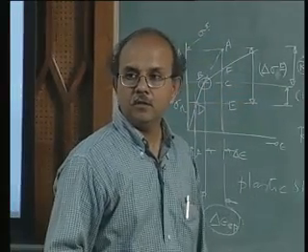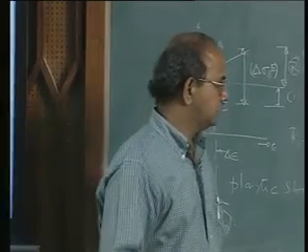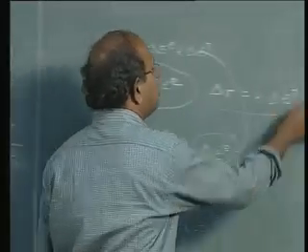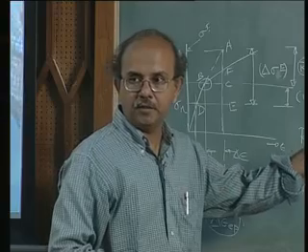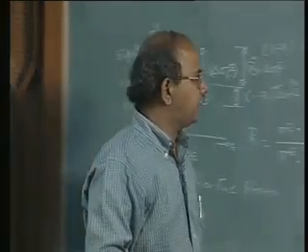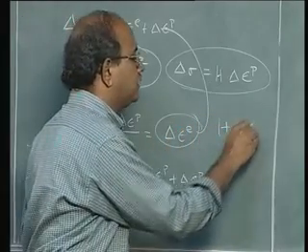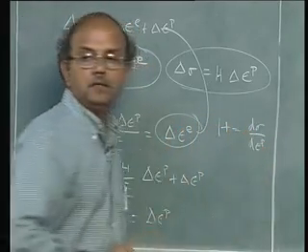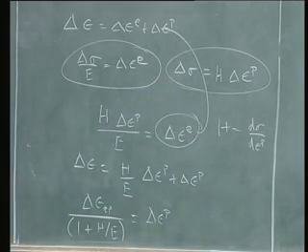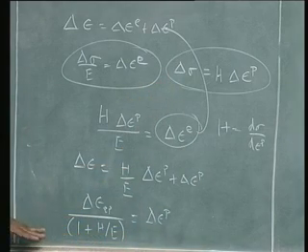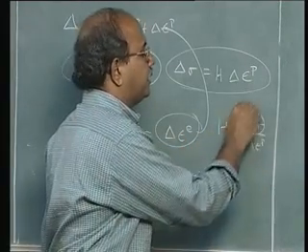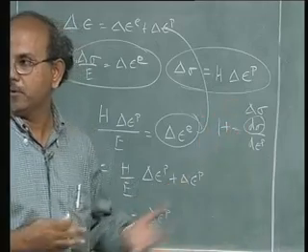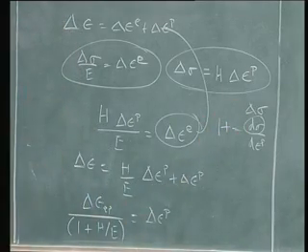Is that clear? Can you repeat how this sigma can be replaced? Yes. These are the two definitions that come from the elastic part of the strain and the plastic part of the strain, because we had defined the plastic modulus h to be d sigma by d epsilon p, from which we get that equation. So together we get delta epsilon to be, yeah, d sigma is replaced by delta sigma, so delta sigma by delta epsilon, because they are incremental, and hence we get this. We are differentiating h and e, so that way we should differentiate.